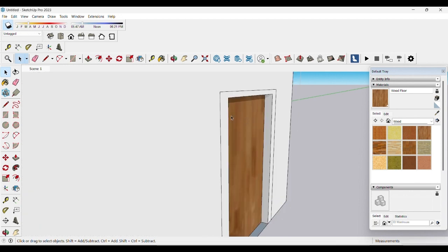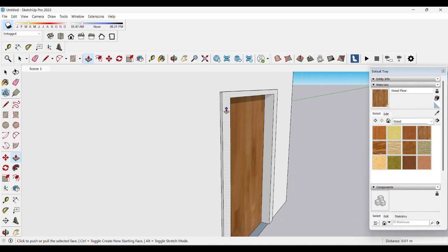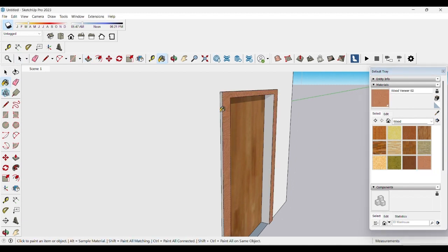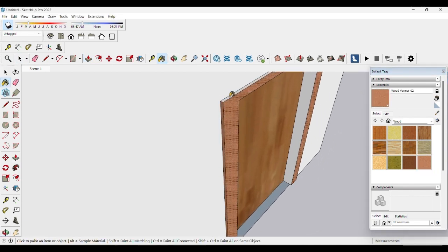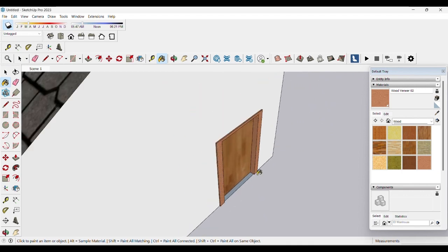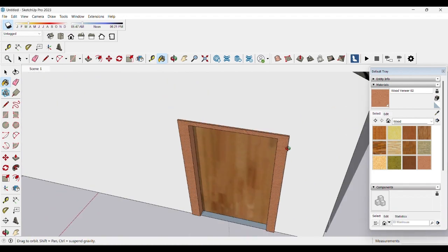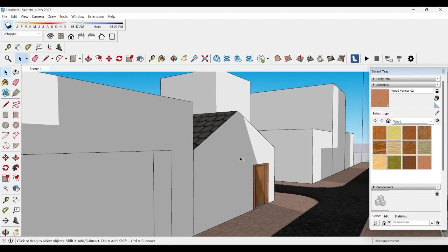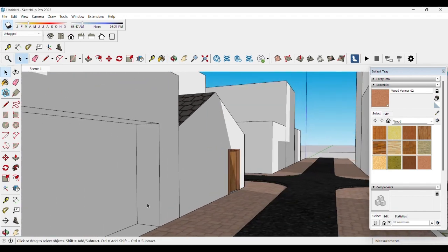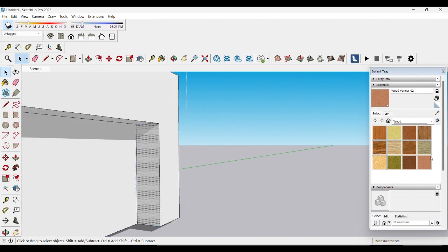Once you double click onto the group object to isolate that viewing plane, you double click the object and type in I. That's the command that gets you out. It lets you come out of the whole model and you can only see this block. And double click that, and you can see the isolation. That's what I was talking about.